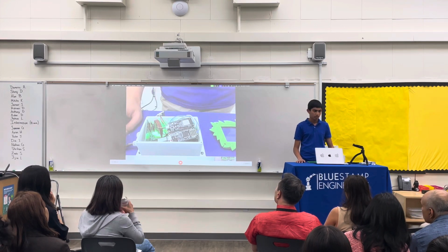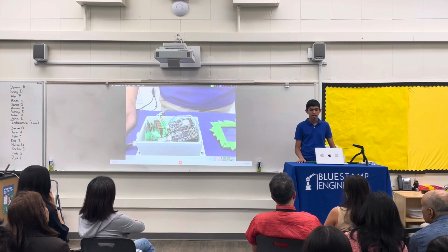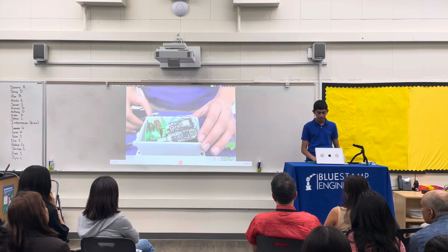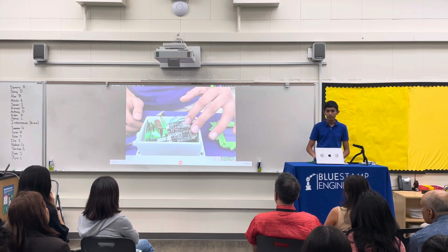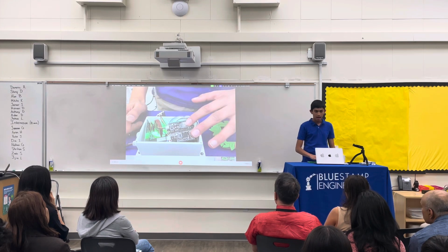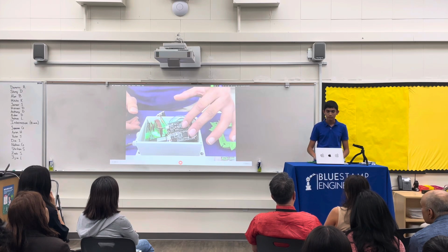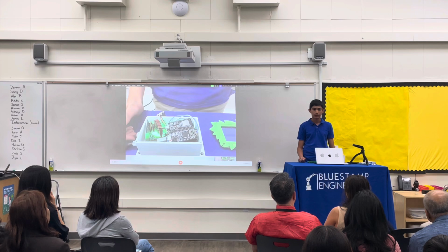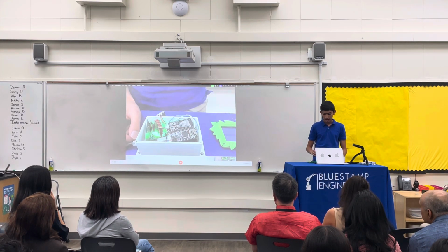Some challenges I faced with this project were connecting to Adafruit.io. The Adafruit.io connection used to drop about 50% of the time. To fix this, I had to research these 2 boards, the Feather M4 Express and the AirLift FeatherWing. I found out that they both connect via SPI, and because of this, they are able to act like an ESP32. So I had to eventually replace these boards, and after that, it was working pretty smoothly.